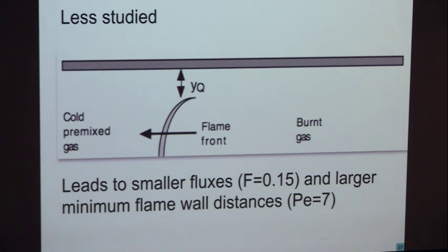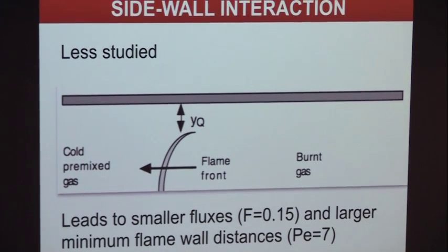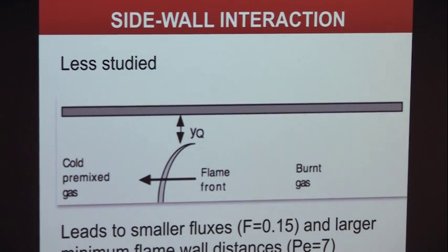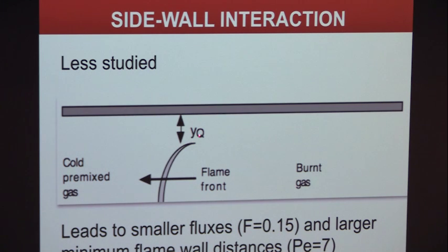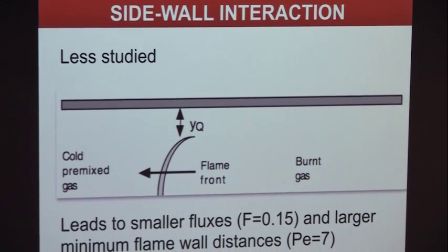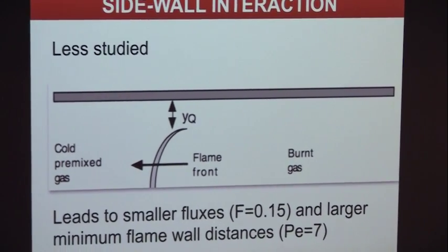For example, you cannot simulate this problem with a code supposing that the flames are adiabatic, because obviously here, these flames are not adiabatic, they are cooled down. Why do they quench? They quench because this zone is cold, and I know it's cold, I cannot go there. I'm burning things with an exponential. If you decrease my temperature, I have to stop, so I cannot enter this zone.